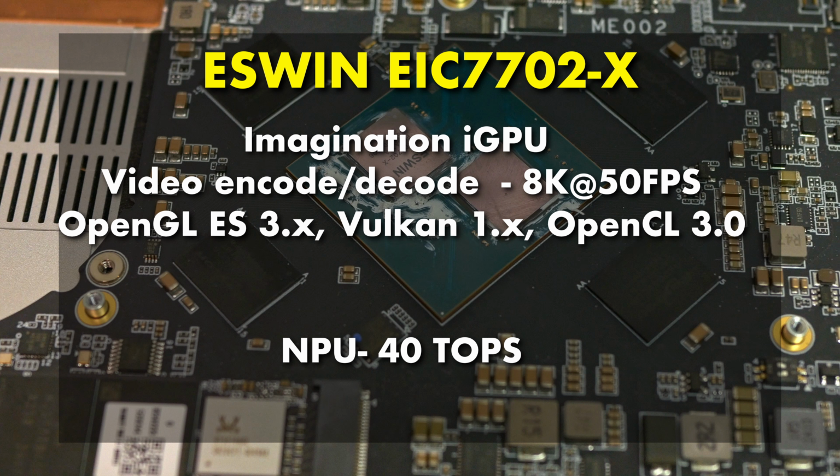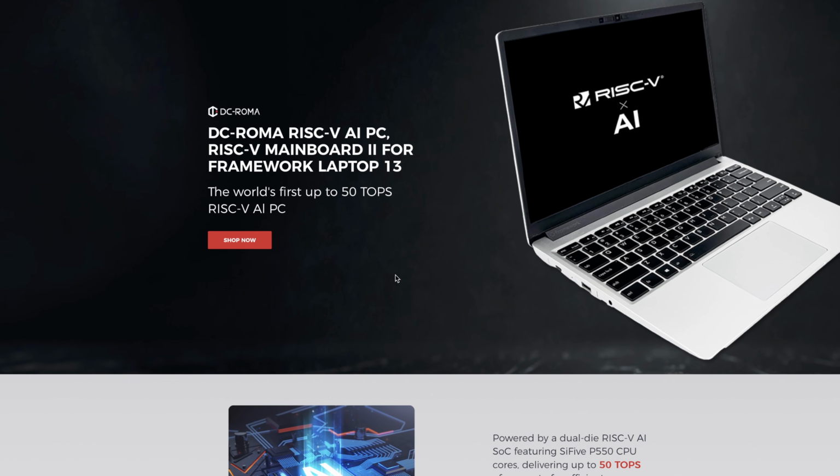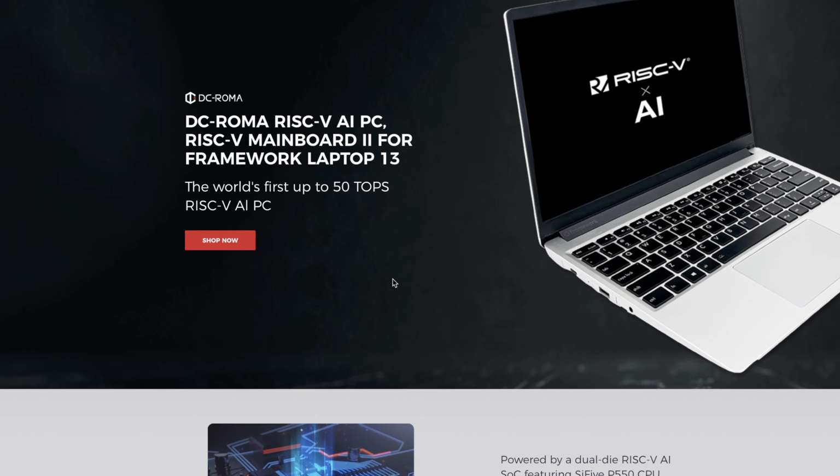What really sets the SoC apart is what's built around the CPU. You get an Imagination GPU for desktop graphics and video acceleration, plus a dedicated NPU rated at 40 TOPS for local AI workloads. The marketing materials claim up to 50 TOPS of total AI compute when you factor in CPU plus GPU plus NPU, but the real story here is that you've got legit dedicated hardware for machine learning, vision models, and inference without dumping everything on the CPU.